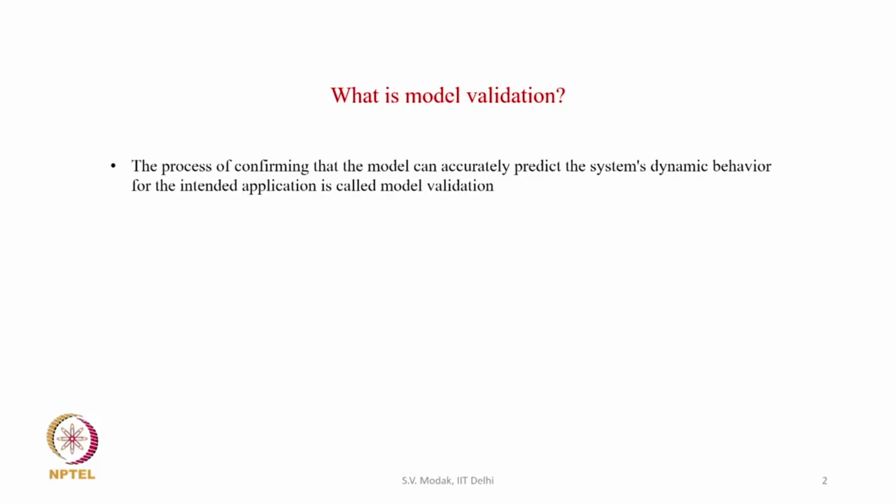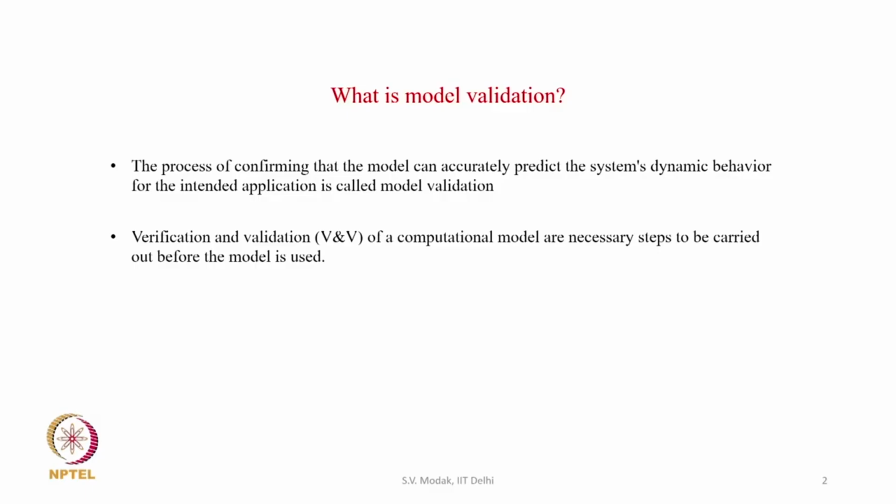So model validation is the process of confirming that the model can accurately predict the system's dynamic behavior for the intended application. So in the finite element model, for whatever purpose it is to be used, we would like to check whether it is accurate enough to make predictions for that application. So verification and validation of a computational model are necessary steps to be carried out before the model is used. So in industrial practice, the verification and validation of the model have become very necessary steps before the model can be used. And what is model verification?